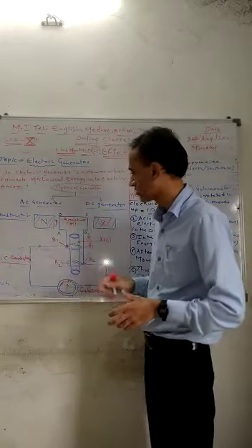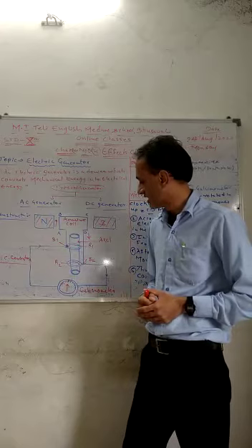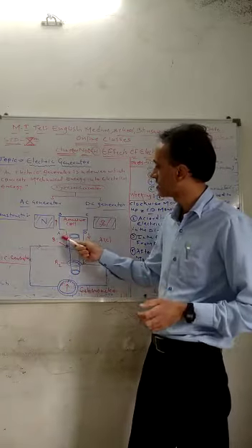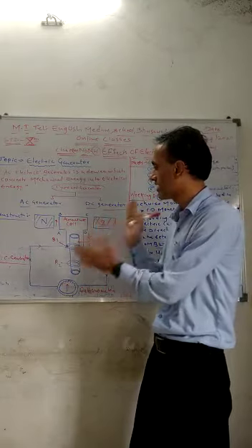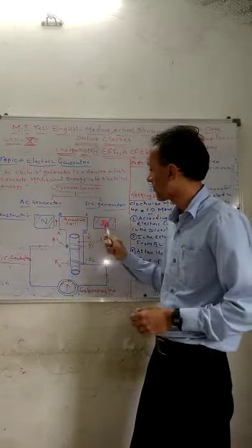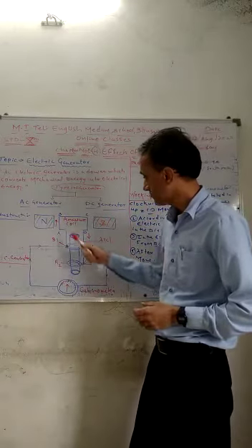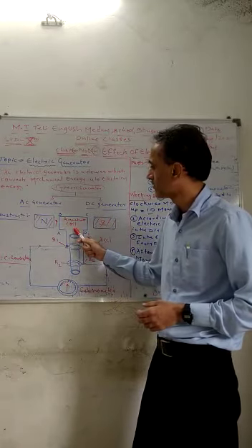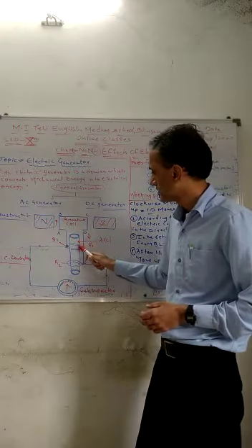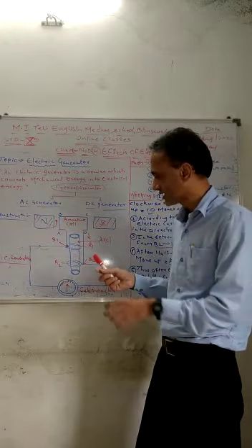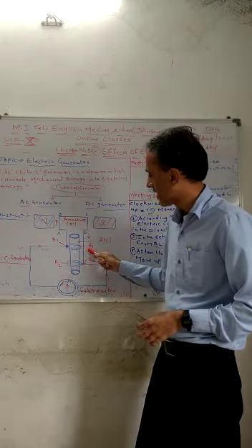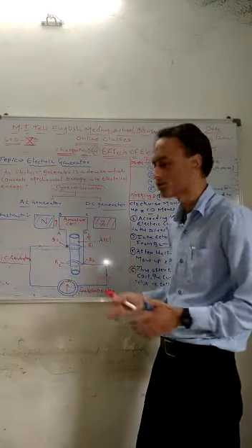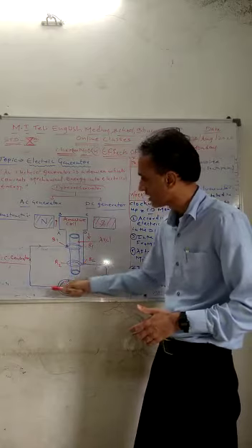So we will discuss today the diagram of the AC generator. The construction shows the armature coil A, B, C and D. It is rotated in the clockwise manner between the two strong magnets. Here you can see the basics of this diagram. This is the north pole and south pole of the magnet. This is the armature coil A, B, C, D. These are the two rings that support the axle. This is called the ring R1 and R2. This is the brush B1 and B2 that supplies the electric current to the circuit, and this is the outer circuit of the AC generator.